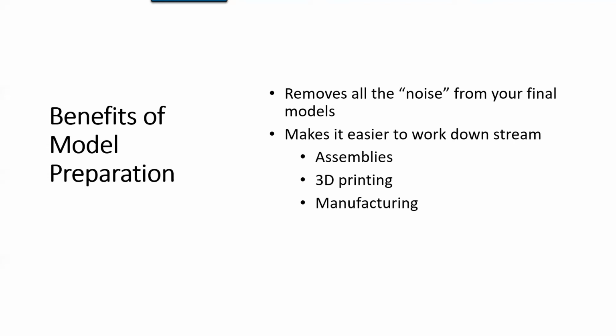And then probably the most crucial one here, at least for me, because this is one of my favorite topics, is that Fusion 360 has CAM capabilities, right? So it has CAM built into the software itself. So you want to make sure that the geometry is correct, that you don't have an extra surface, especially if you're going to be creating some sort of a soft jaw around the model to clamp the part in place. You want to make sure that you don't have any excess geometry that's just not needed, right? So making sure that you have a nice clean model to begin with is going to ensure that you have a nice, in this case, 3D print down the road.